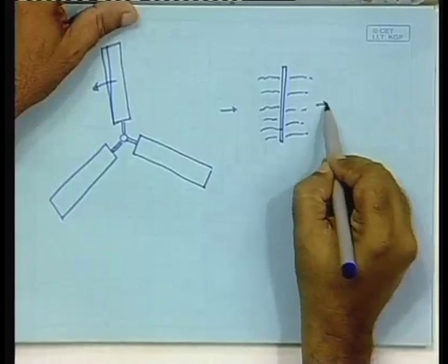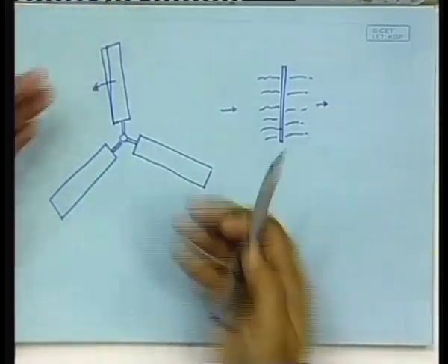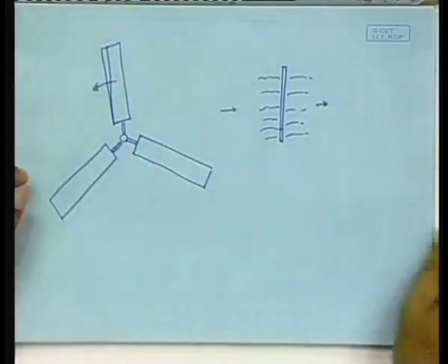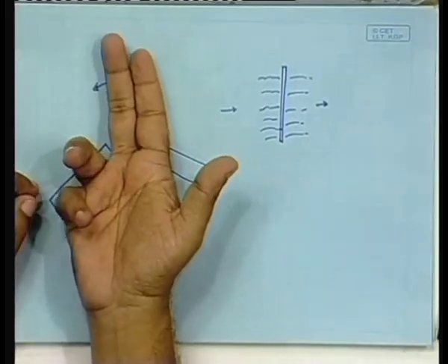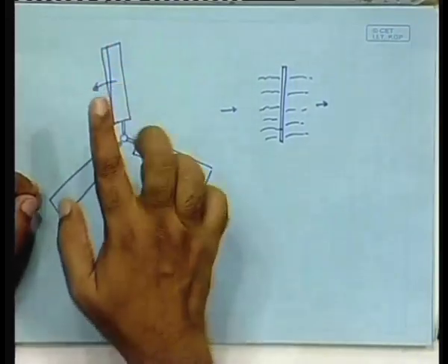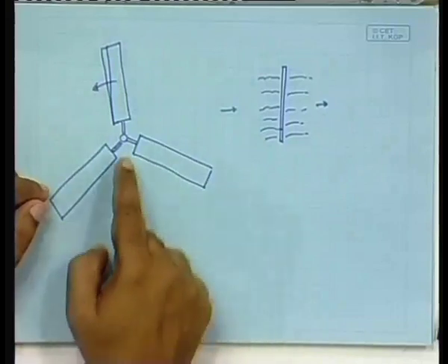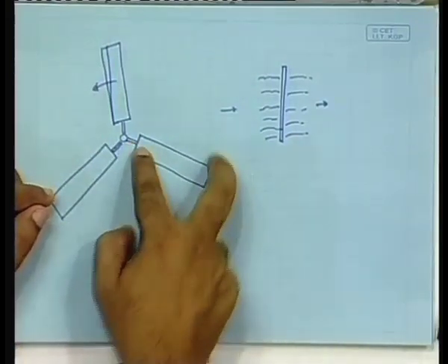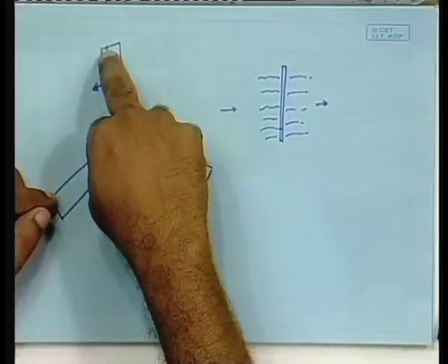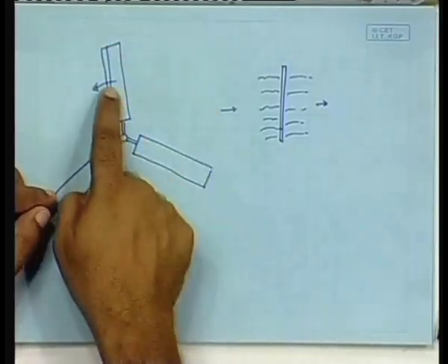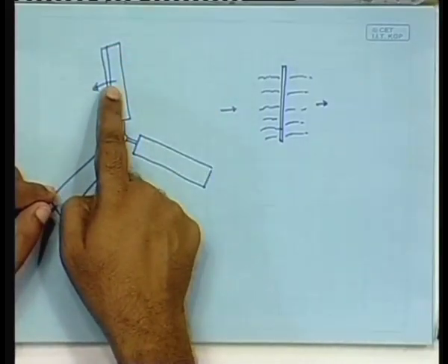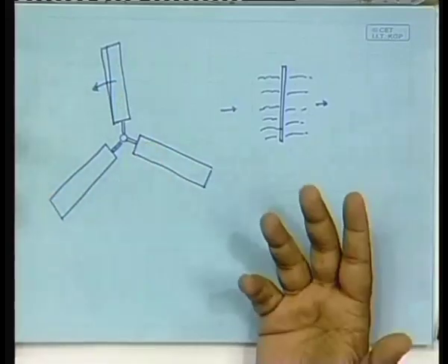So, the blade is rotating, and as a result it is disturbing the wind, both upwind as well as downwind. Now, if it so happens that the next blade comes into the position taken up by this blade before the disturbance passes away, then obviously it will run into a disturbed wind.